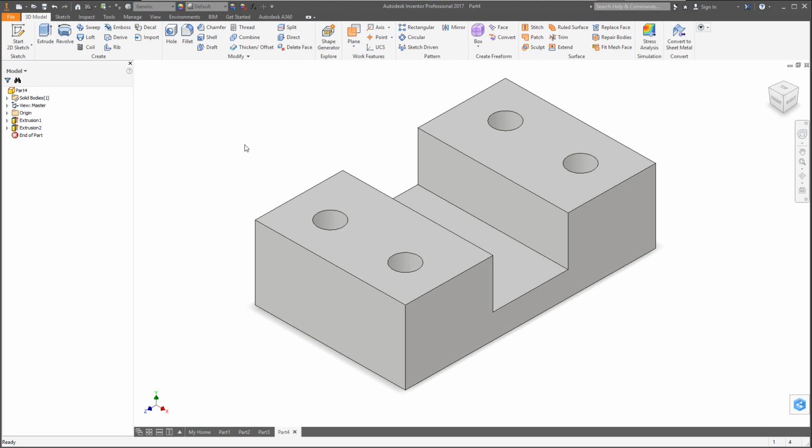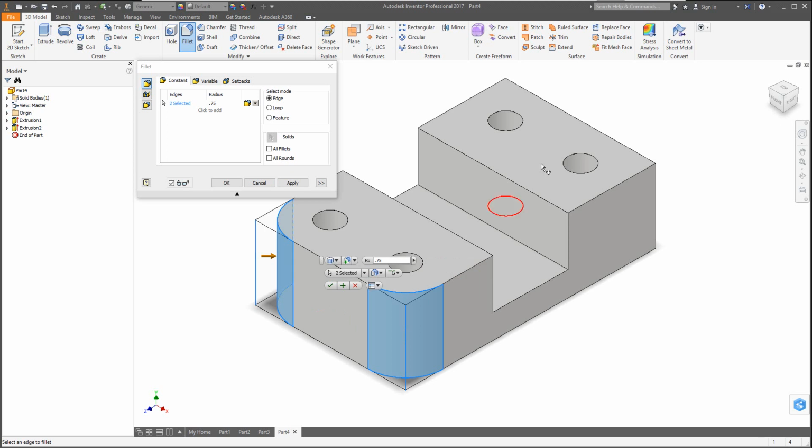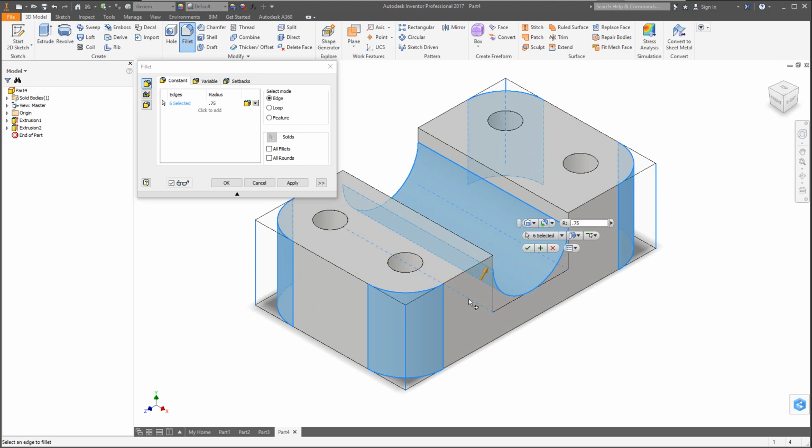But if you're going to make a portfolio, I would recommend enhancing this a bit. Play with it and put fillets on and chamfer. So I'll just go through that really quick. Like for example, the fillet tool here. I'm going to go ahead and put in 0.75 for the radius and select all 4 corners. And I'll even select these inside edges here and here.